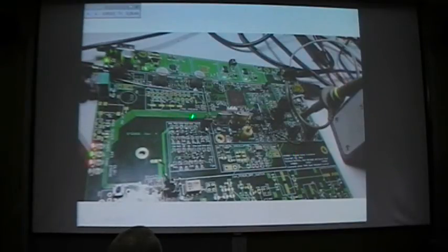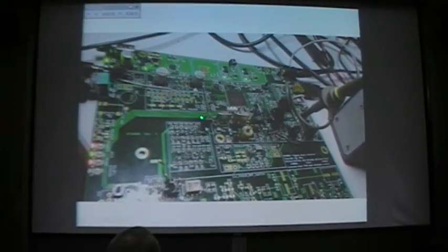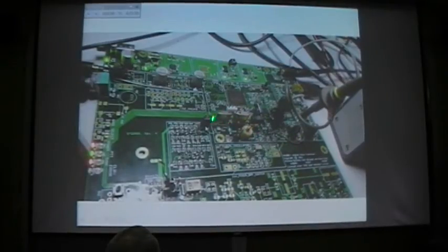So things like these headers here, I'm not sure if you can see that clearly, but little 4-pin header that we can just hook a spectrum analyzer up to, and signal generator. There's another one on the other side of this block, so if we hook one up here and hook one up here, we're testing the crystal filter section in isolation. If we hook one up here, then we're testing just the baseband amplifier. So designed for test and for radio newbies like me.